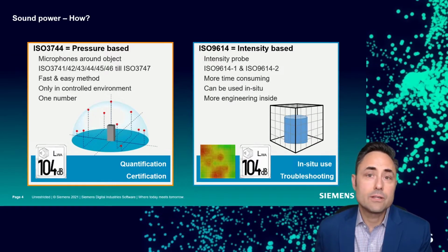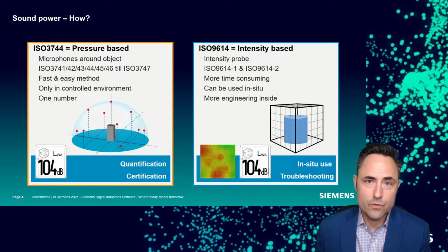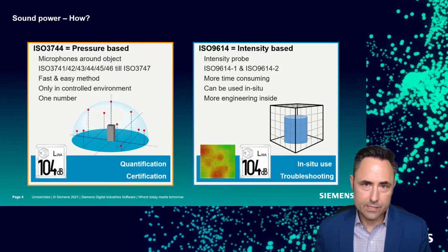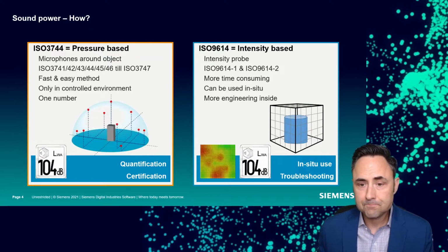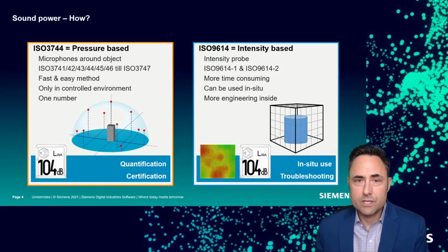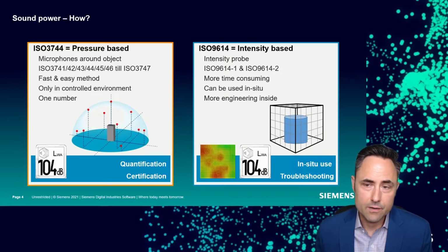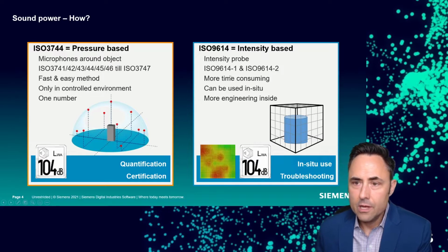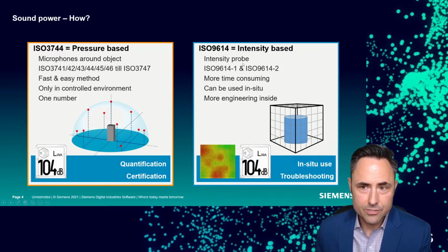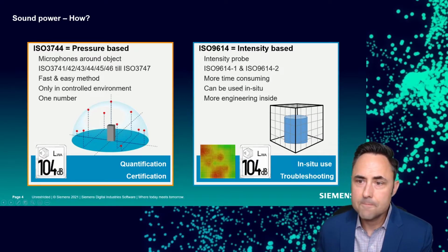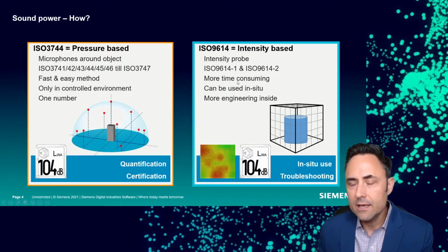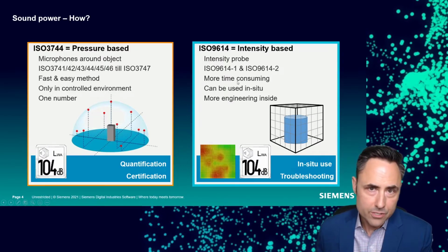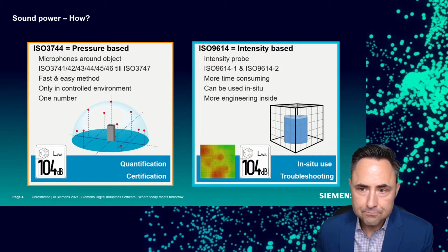So when we were talking about sound power, this objective number that we use for the inherent sound making capability of a device, we talked about a sound pressure method to get there. But there was also this sound intensity based version, and that's what we're going to start with right now. It's got its own ISO standards. It's got its own equipment that you use. And as we'll see, it can be more time consuming to perform.